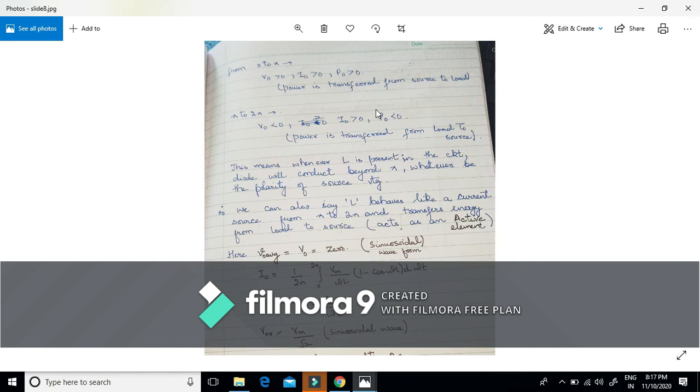This means that whenever there is an inductor present in the circuit, our diode will conduct beyond pi, whatever be the polarity of the source voltage. We can also say that this inductor behaves like a current source. That means whenever it's supplying energy from pi to 2 pi, basically it acts as an active element.